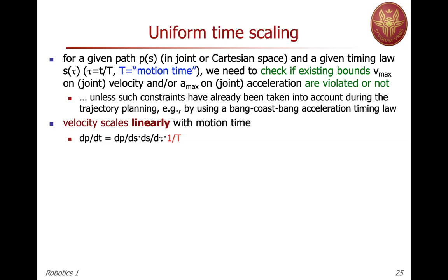So just modifying the total motion time, it means that in the meantime, we are following the same type of profile, but scaled over time. Vice versa, if we realize that the 2.5 seconds was too slow with respect to the capability of my bounds, so I'm really well within the bounds, I would like to speed up motion and reduce from 2.5 seconds of total time to, let's say, 2 seconds, 1 second, 0.5 seconds, and so on. So it's not a matter of trial and error.